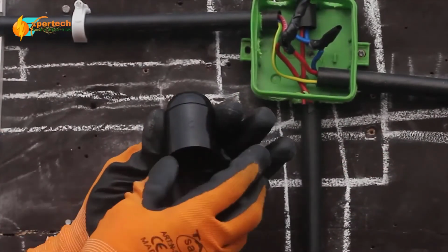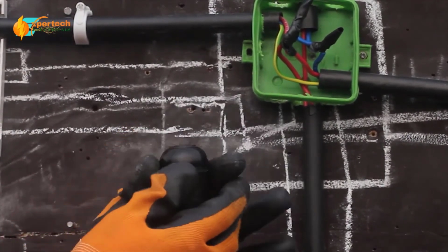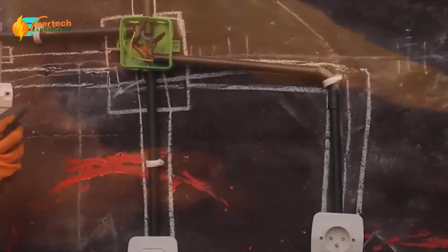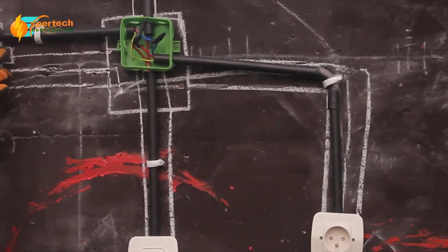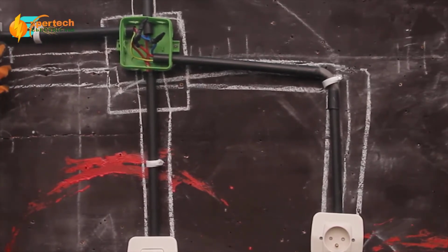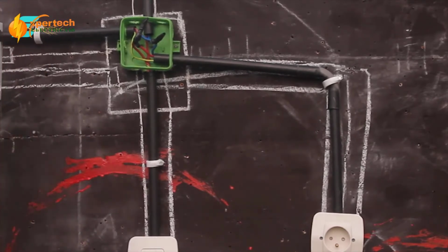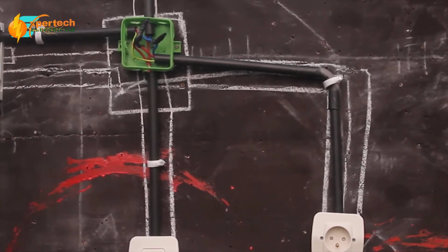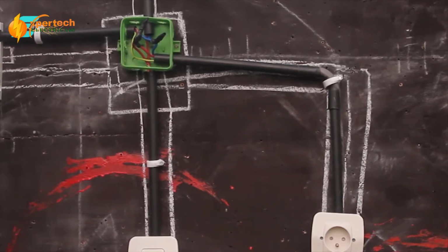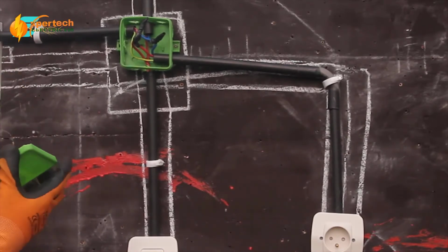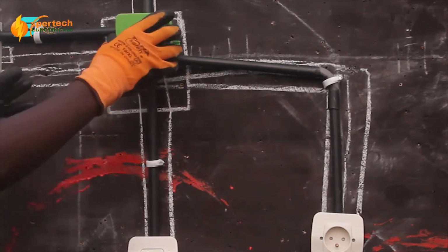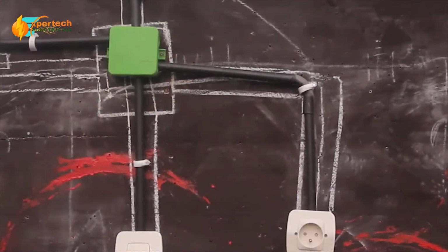When we finish, we bring the lamp holder and you connect the cable into the lamp holder in order to be fixed well. As we finish connecting the lamp holder, what we do, we are going to close our distribution box. And then we also close our junction box. As we are learning together, I hope you keep doing practical exercise with me.